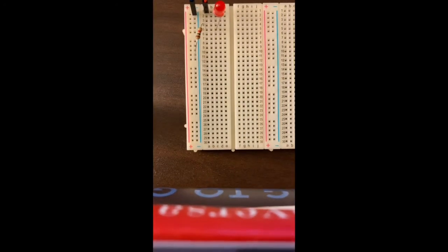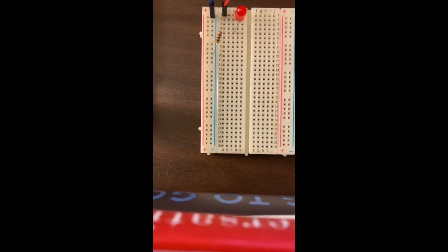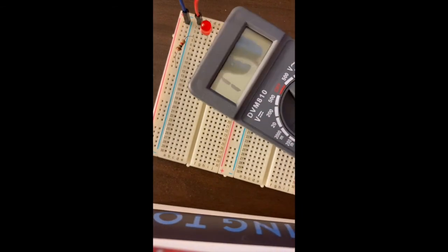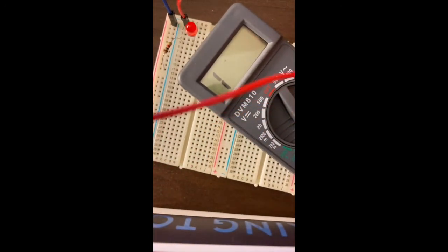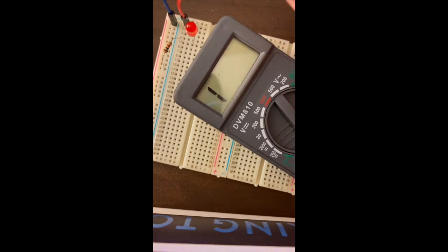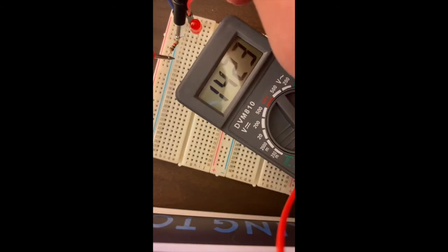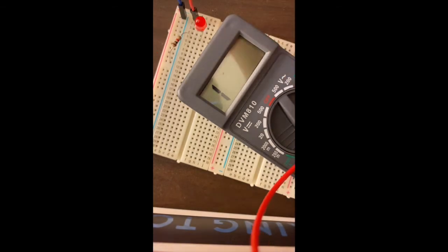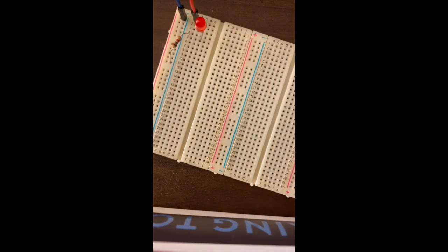Another cool thing you can do is check the resistance value of the resistor using a multimeter. I've got a cheap one here that I'll show you. Basically this multimeter will display the resistance value if I connect these leads across the resistor. So I should be able to touch both sides of the resistor, and it will give us a reading as to how many ohms the resistor is. So we're getting, my hands are wobbling and stuff, but it's in the neighborhood of 1,000 ohms. So that kind of proves that we read the bands correctly.